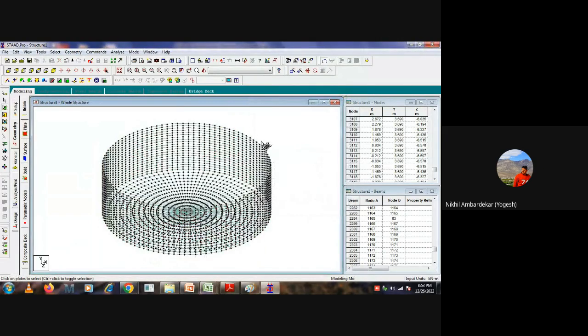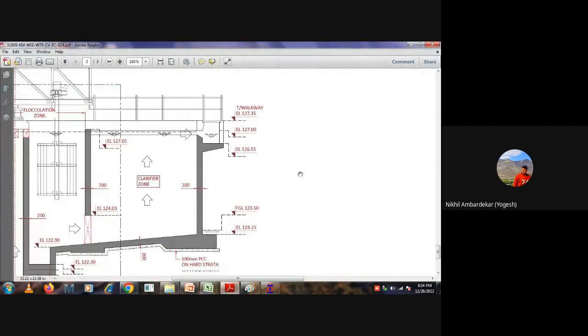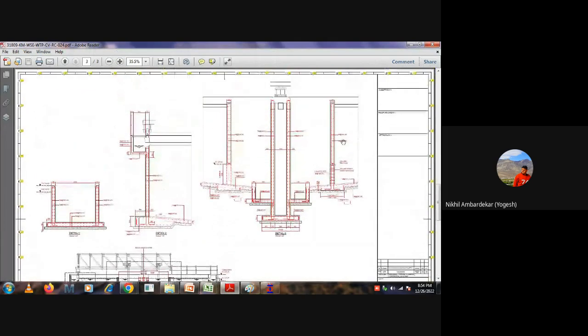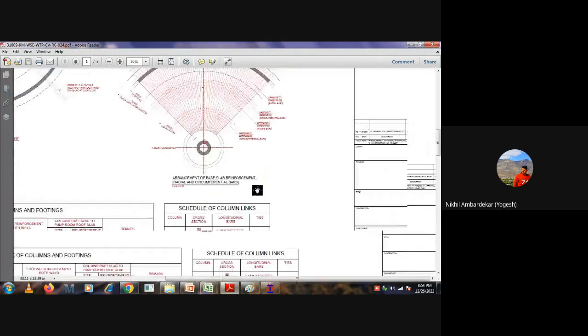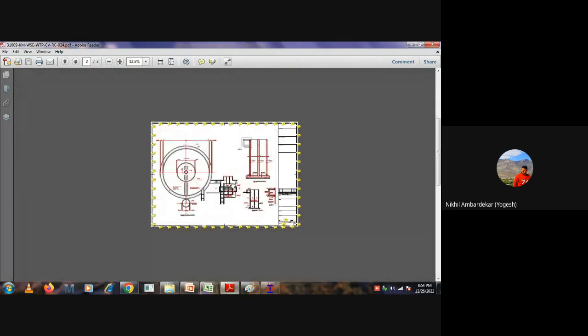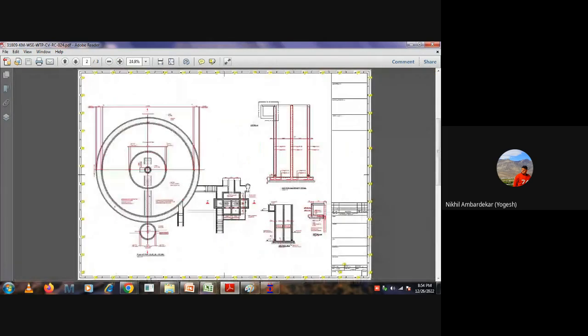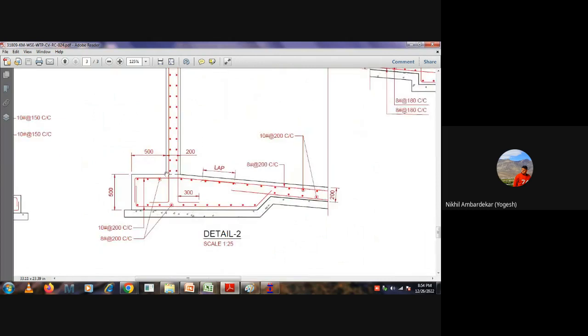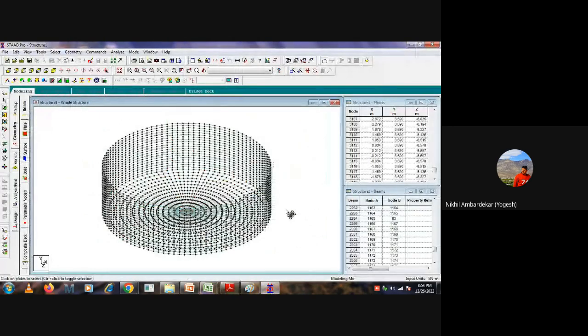So next we need to add the toe also. How to add that toe? What is the toe width? It will be mentioned somewhere. Toe, yes, 250, 500. Okay. So center to center, 100 plus 500 means 600 that we need to go beyond the wall center, because we have 200 mm thick. So from wall center to wall edge, 100 mm, plus 500.